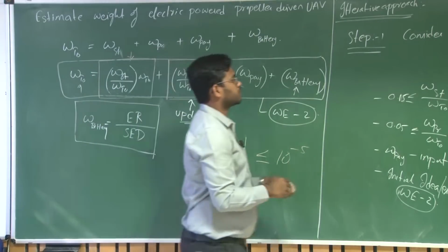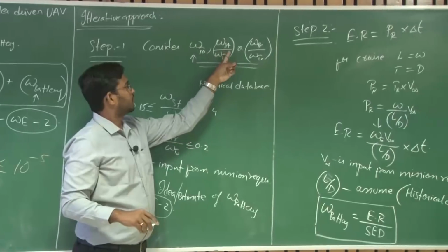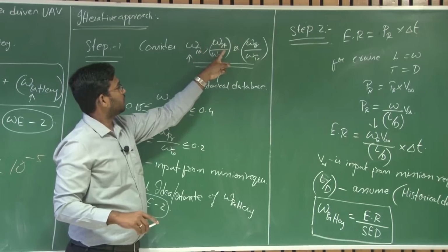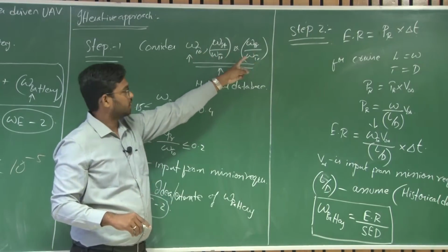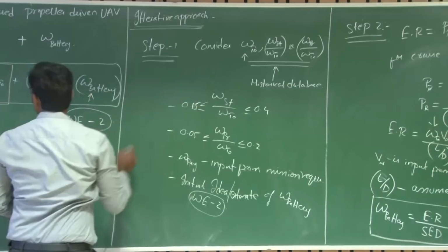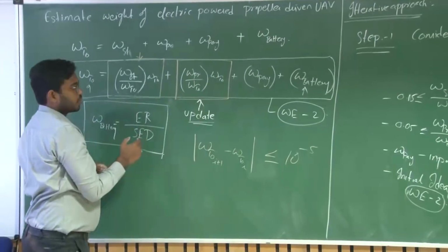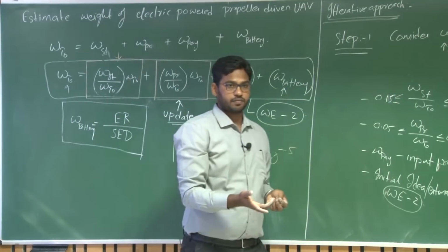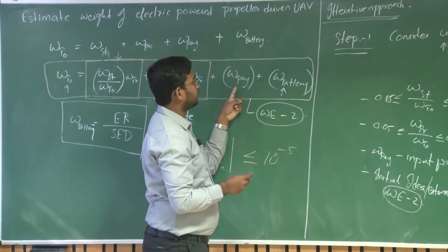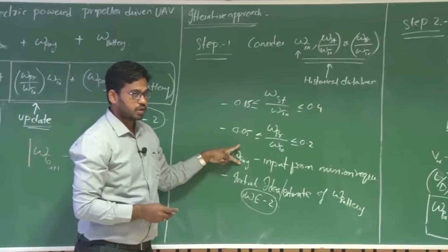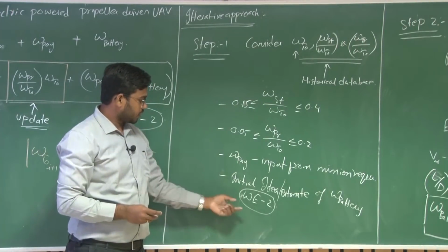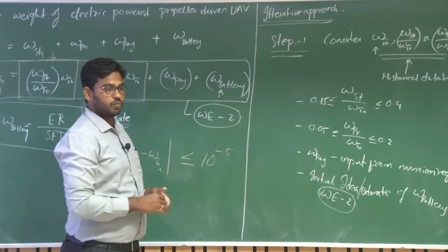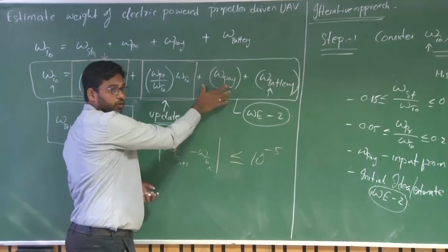So the three inputs that you considered are W takeoff, at i equal to 0, the 0th iteration, to start with, the structural weight fraction and the propulsion weight fraction. Now once you have this, with the same equation, what you can find out is the battery weight with the new payload that you are going to carry. Payload is an input here. So at i equal to 0, you have the corresponding battery weight. What should be the corresponding battery weight for this new payload to carry?